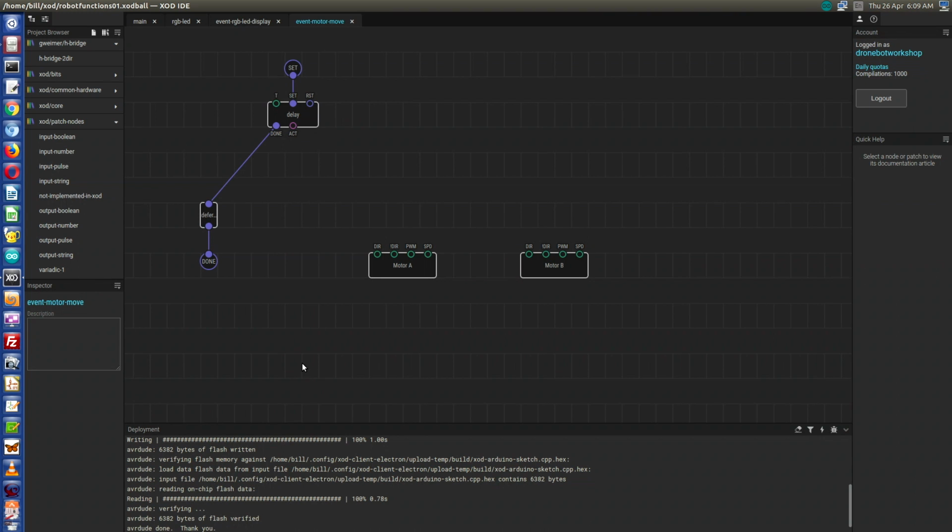And do that. Okay, now if you think about it, our H-bridges have 4 inputs. 3 of them are the inputs to the dir and the not dir, which are the IN1 and IN2 pins on the L298N, and then the PWM, which is the enable pin. And then we've got a speed input, and this is the value from 0 to 1 that we want it to go, or from -1 to 0 if we want it to go backwards. And so 3 of these pins can actually be passed directly outside of our node right now.